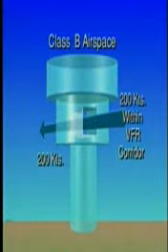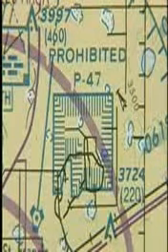Warning areas are over coastal and international waters and cannot be designated as restricted. However, the activities within these areas may be as hazardous as restricted areas. An alert area contains a high volume of pilot training or an unusual type of aerial activity. Flight within alert areas is not restricted, but you are urged to exercise extreme caution and remain alert for other traffic.